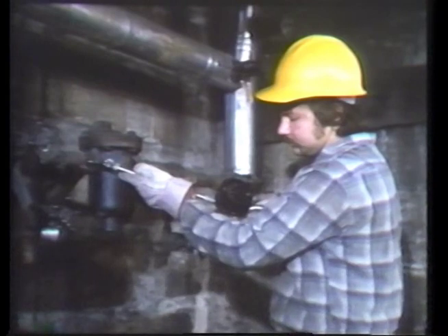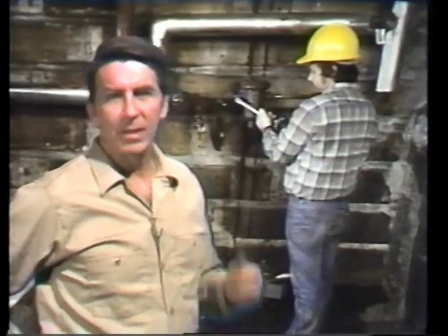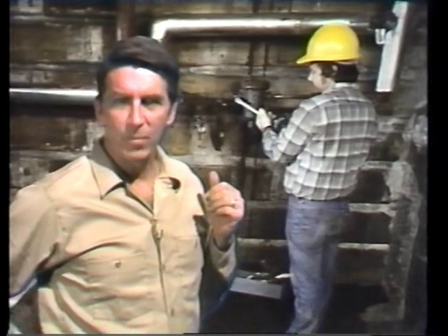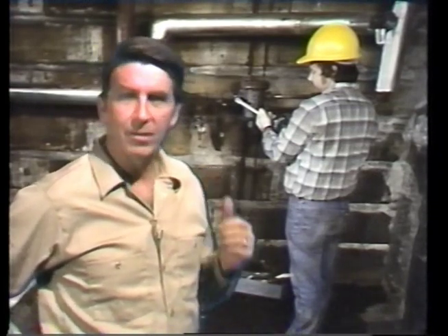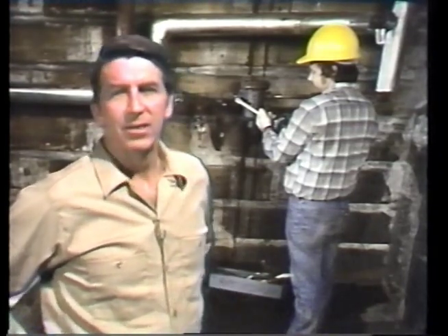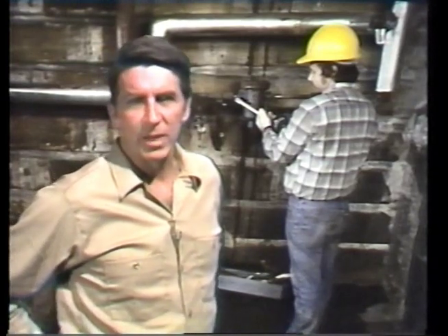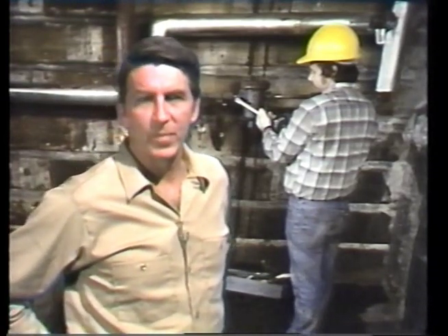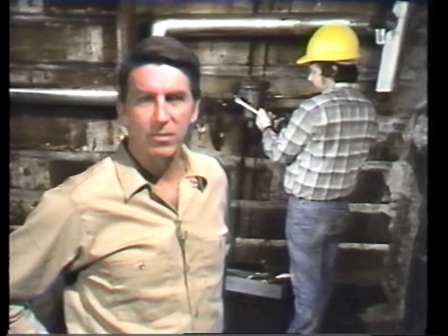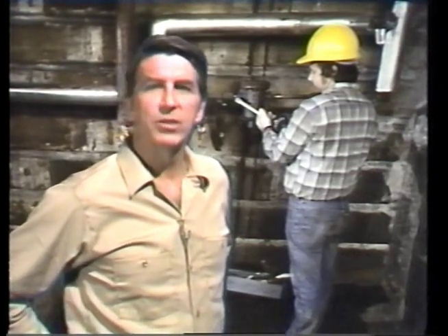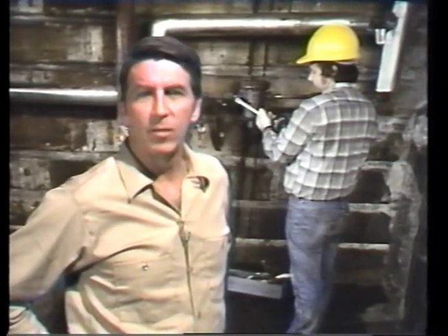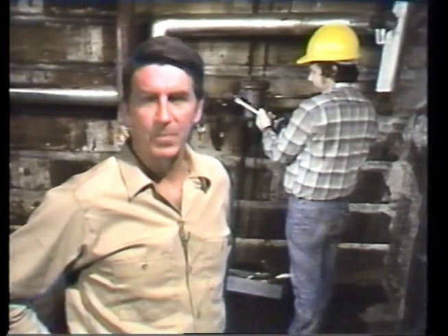Okay, now let's consider the temperature at the trap outlet. If the trap outlet temperature is too high, the trap may have failed open or the outlet piping may be clogged. Use either a sound or visual inspection to see if the trap has failed open. If it has, it must be replaced or repaired. If the temperature at the trap outlet is within the allowable range, conditions are normal.